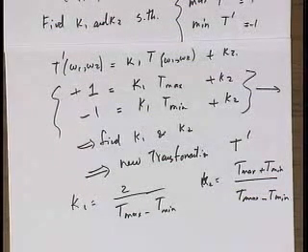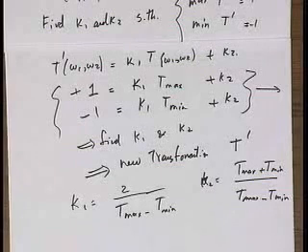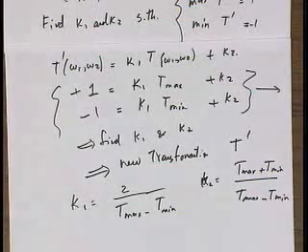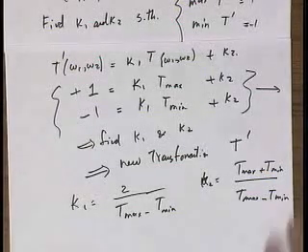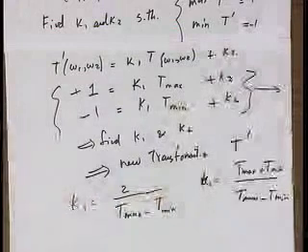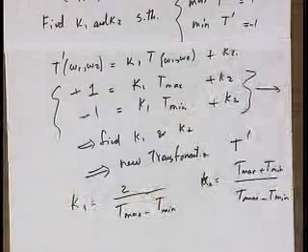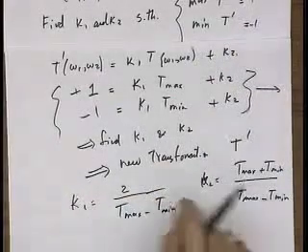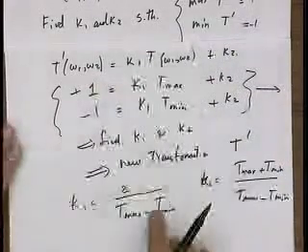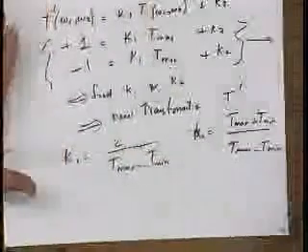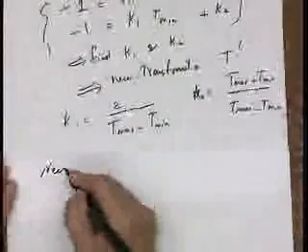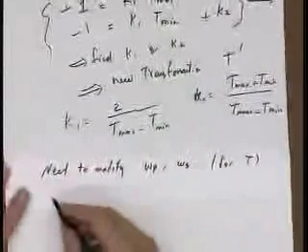That's just a linear transformation of the omega s and omega p for the tentative filter that we had just designed. We had that t of n1 and n2, and that resulted in some omega s and omega p, or we picked some omega p and omega s associated with it. So now that we minimally perturb t to get t prime, what you can show is that we just need to modify the old omega p and omega s that we had for t as follows.